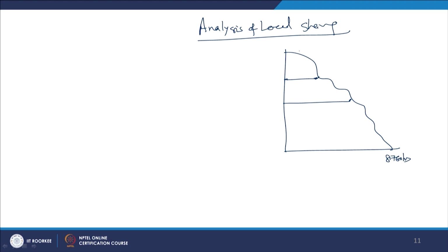So, duration and load curve we have drawn. This is the power in kilowatts, right, and this is the H hours per year. Suppose this load will remain H hours per year, right. So, we choose certain base load. Suppose let us say this is base load. Somewhere we have to draw a line. You can take base load as this. In that case, during the remaining period, the plant will be underutilized. If you take base load this, in that case, peak load has to work for a longer duration of time. So, some optimum value has to be realized between peak load and base load.